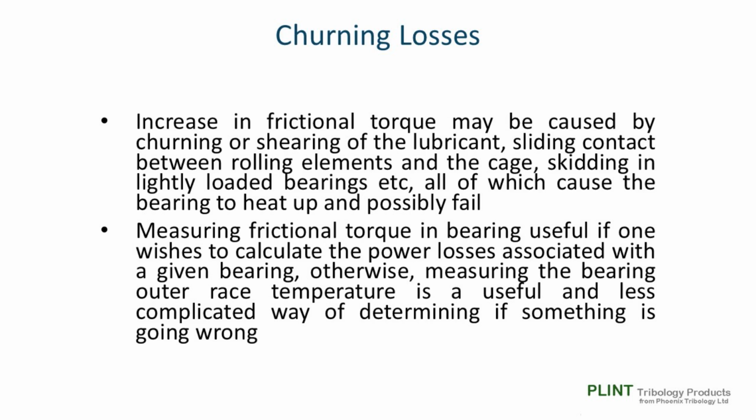It only becomes of interest in more specialist circumstances, usually associated with operating bearings at very high speeds. In this case, the increase in frictional torque may be caused by churning or shearing of the lubricant, sliding contact between the rolling elements and the cage, skidding in lightly loaded bearings, etc., all of which cause the bearing to heat up and possibly fail.